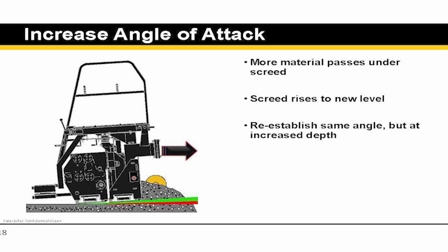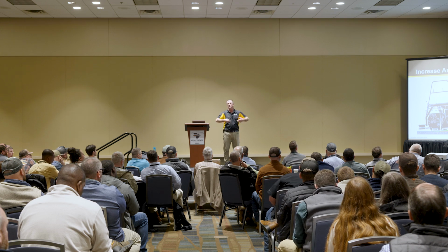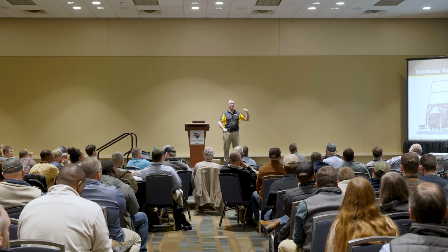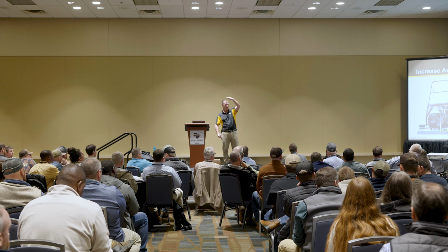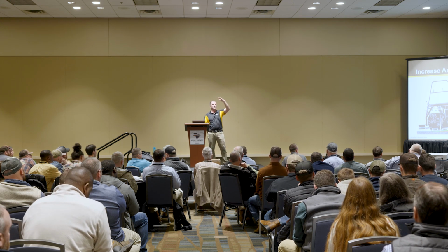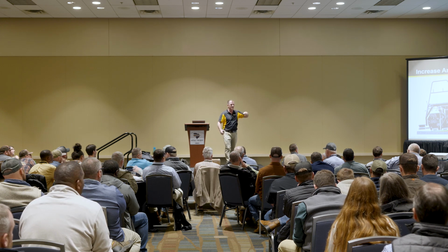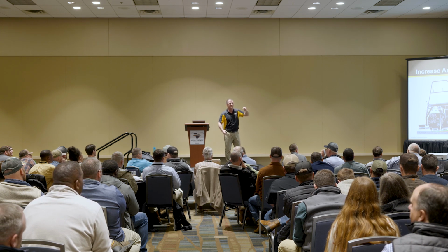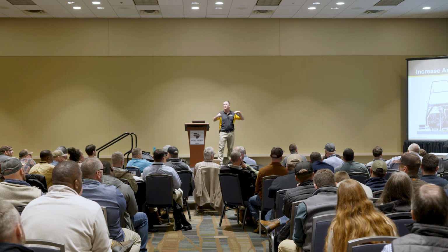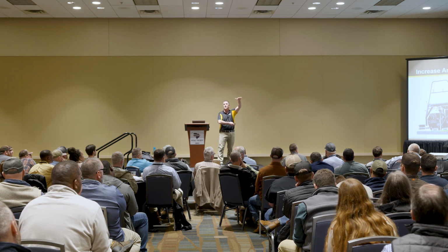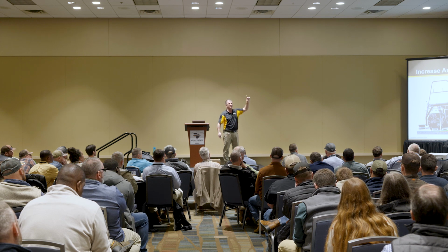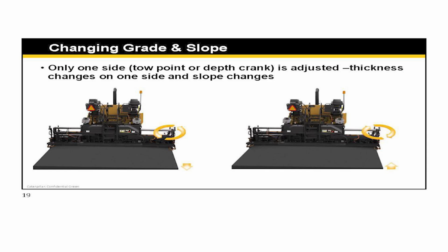So what does that do as far as mix coming in? That's a lot more mix in, right? So what's that screed do? It climbs, right? So I go to a new thickness if I raise my toe points while I'm paving, or if I go positive direction with the depth cranks. So I introduce an angle of attack, I let more mix under, I go to a greater thickness. If I go the other way, it just does the opposite, right? I go from thicker to thinner.